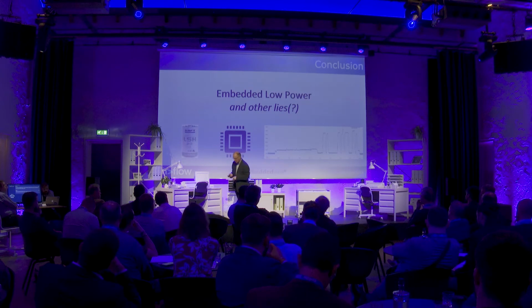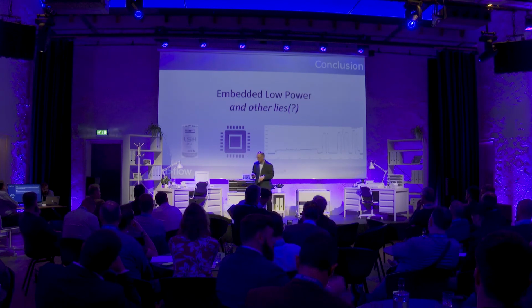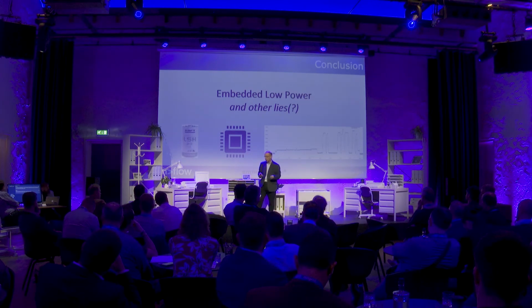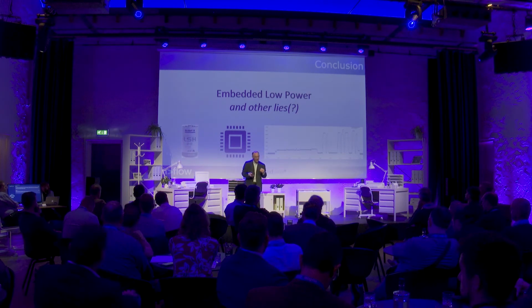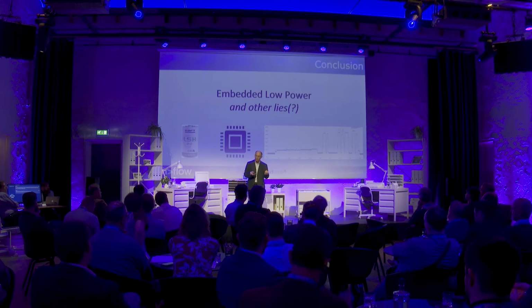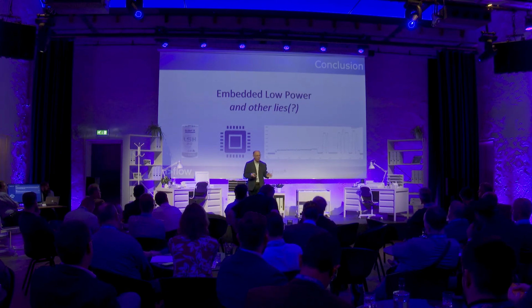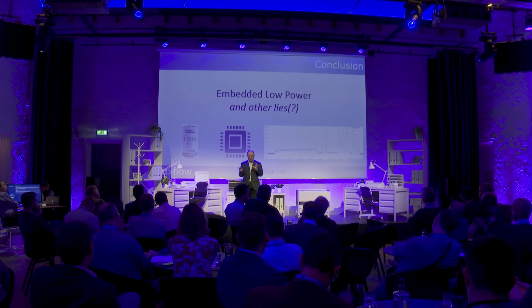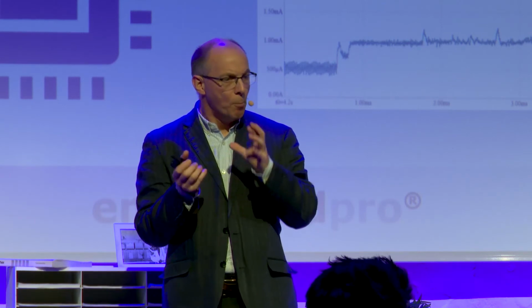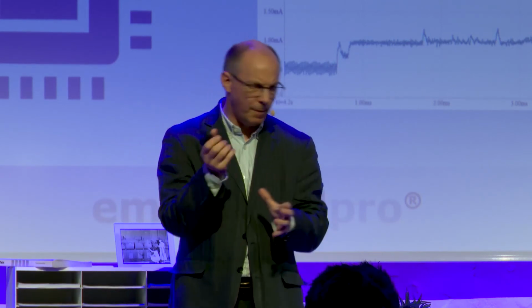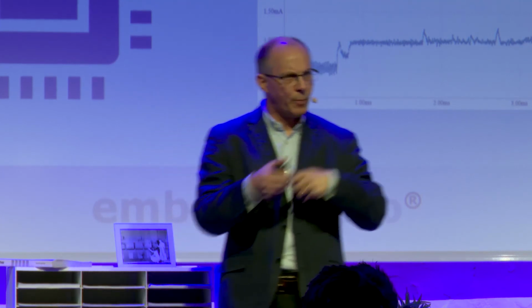In asset management, sleep mode is okay, but for live tracking, how can we increase battery life? This is a tough one. It depends how we want to wake up the unit. We want to be in low power mode all the time, as much as possible. But of course, if the unit is moved when it should be in a dock, in a container, and isn't expected to move, we want to be able to trigger a wake up.